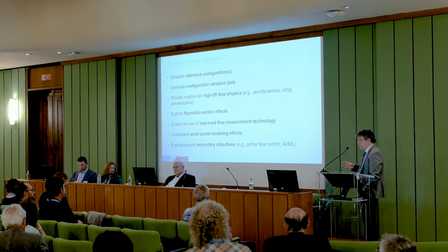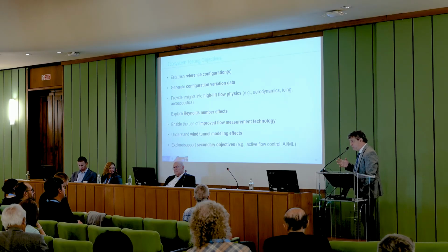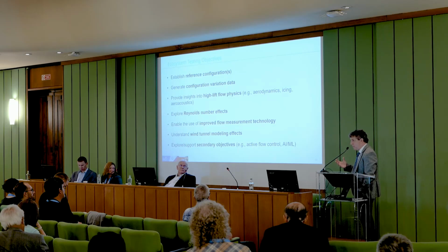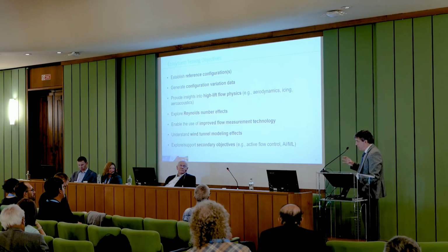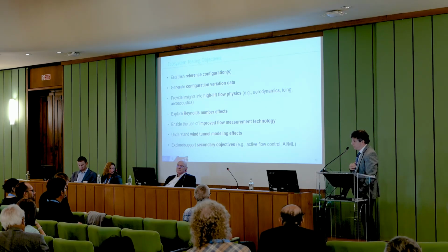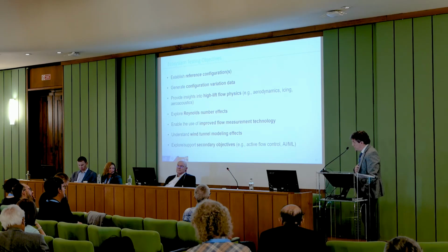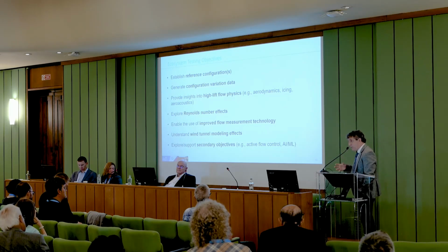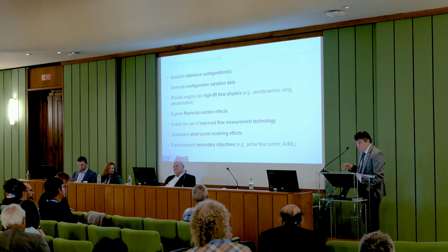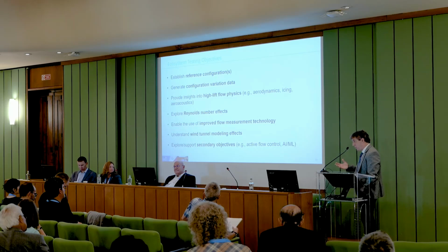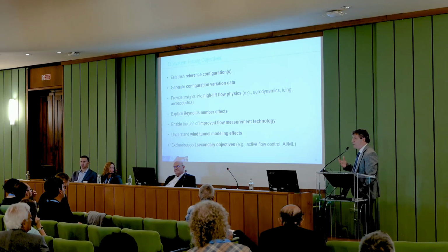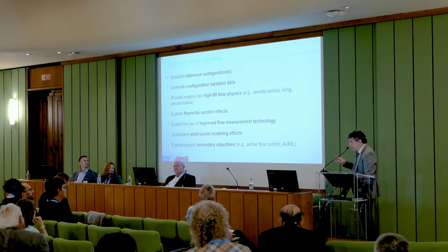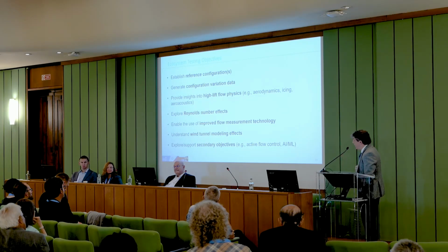We want to utilize the testing in the most effective way to look at flow physics. So again, you can look at the forces and moments, and unless you understand what is actually happening in the flow, you may get the right answer for the wrong reasons. And we've seen that a lot, particularly with RANS, as you get close to the stall. And so we want partners to not only collect ecosystem data, but really study the flow physics. So surface visualization, off-body visualization, those things are kind of critical. And we're learning that we wish we had a whole bunch of other data, right? Because the physics is so complicated that you need multiple corroborating sets of data to really understand what's happening. So that's really a focus.